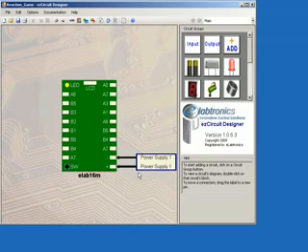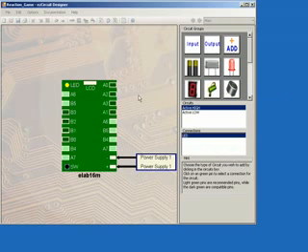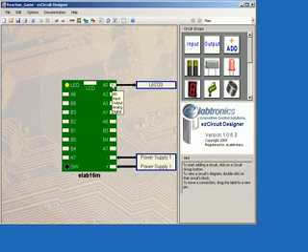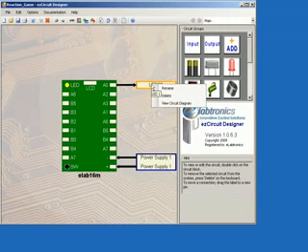First off, we'll place an LED by selecting the LED icon in the Circuit Groups menu and then clicking on the A0 pin. We now want to rename this LED by right-clicking on the label, selecting Rename, and calling it Player 1 Green. And then hitting the Enter key on the keyboard.